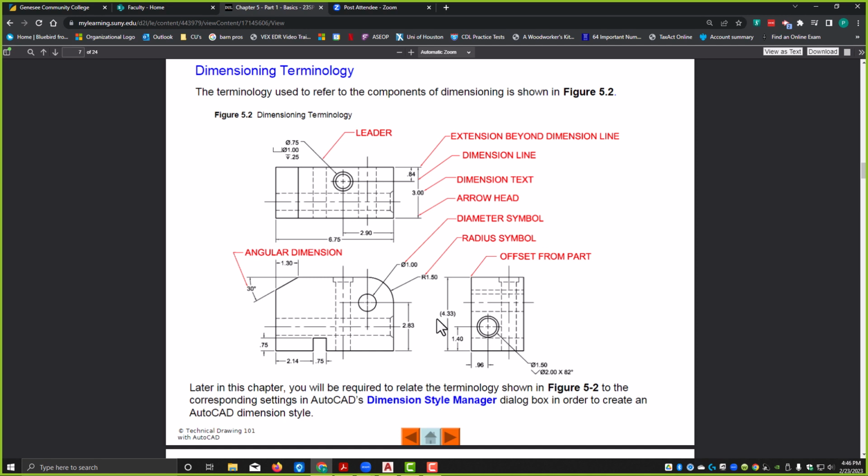It can be useful sometimes in dimensioning of parts, but what I find is that it's kind of confusing. I don't like to put that type of parentheses in. And if you do this kind of thing, it's called over dimensioning. When I correct a drawing and I see this type of thing, I will put what's called a double dimension mark on it. So I'll write DD on it, and that stands for double dimension.